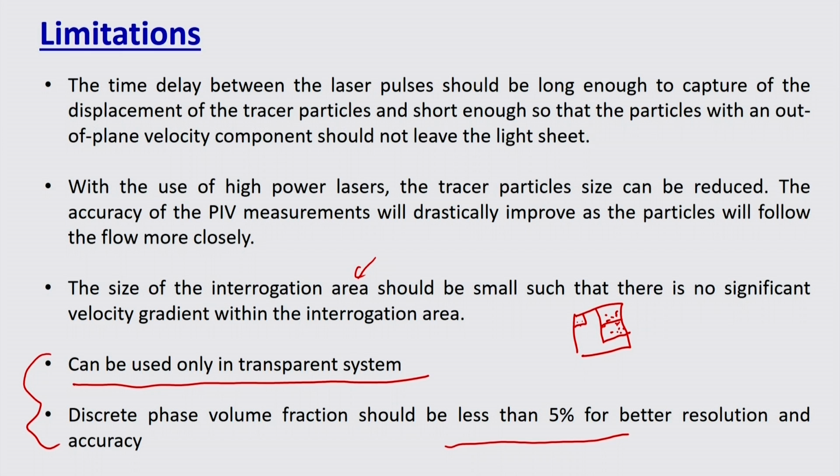Okay. So, that is the major limitation of all the optical based techniques, and that is why the next generation of improvement has been done and new techniques have been developed, which are based on radiation, mostly gamma based radiation. We know that gamma radiation can penetrate almost anything, and the losses will be very small unless you are using a very thick wall to stop all the radiation. That is the next phase of development, the radiation based techniques, and mainly two techniques we will discuss. One is positron emission particle tracking and the other is radioactive particle tracking.